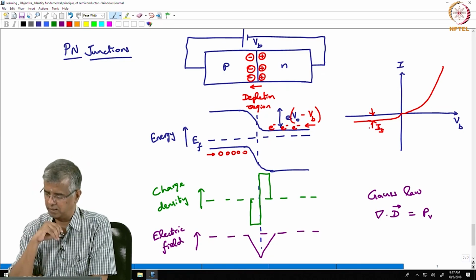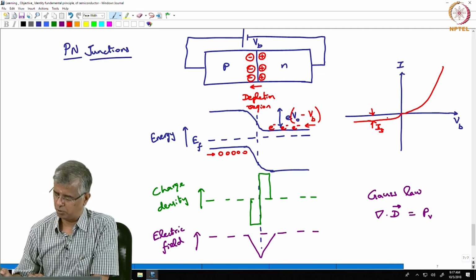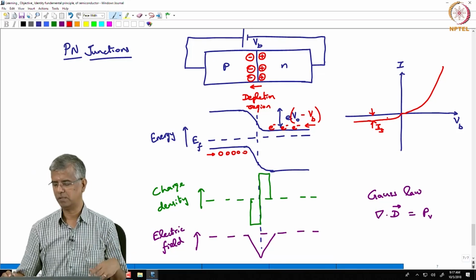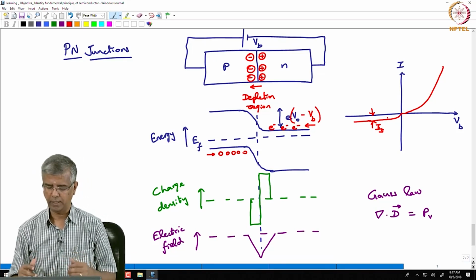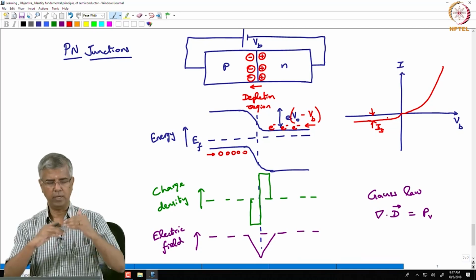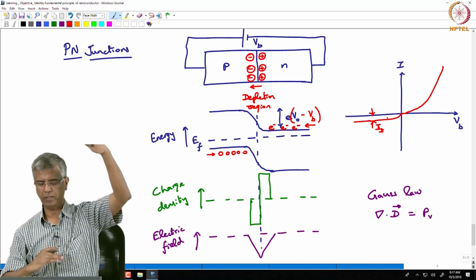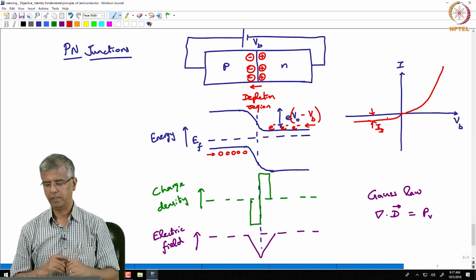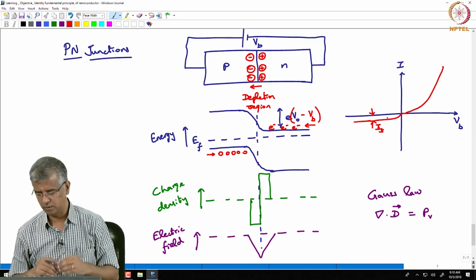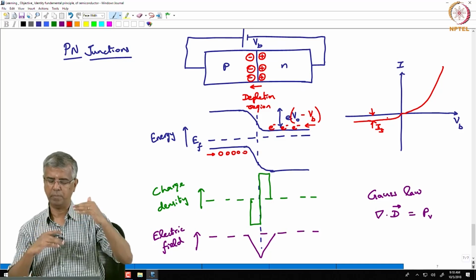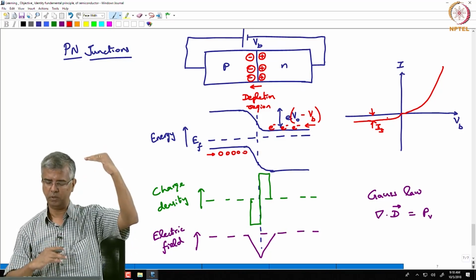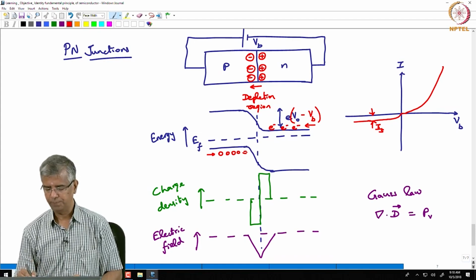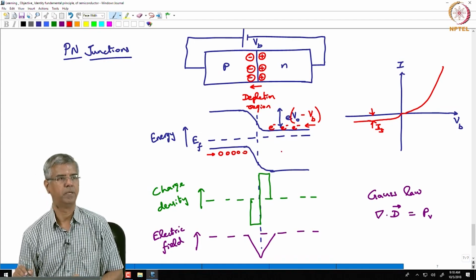just capital IS, right. And of course, if you keep increasing that reverse potential, then these two layers keep going further and further apart. I mean the conduction band on either side is going further and further apart, so that you may start seeing tunneling phenomena happen.